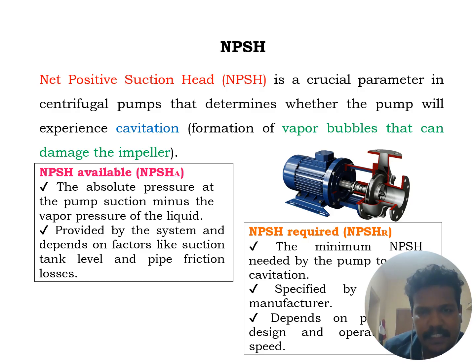In many cases, VFDs, variable frequency drives, are installed to reduce pump speed without understanding NPSH properly. Changing the speed may or may not affect the NPSH value, and improper adjustment can lead to cavitation damage. However, this is a separate topic which we will discuss later.